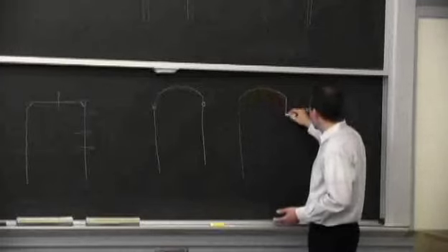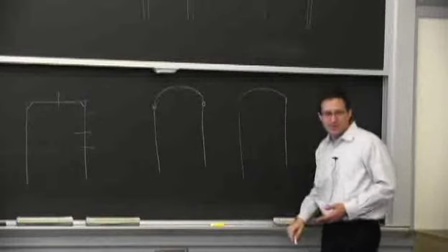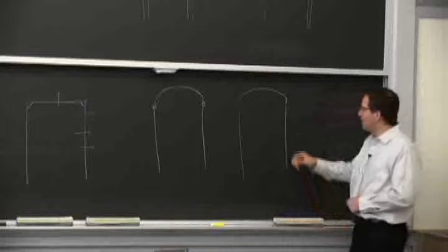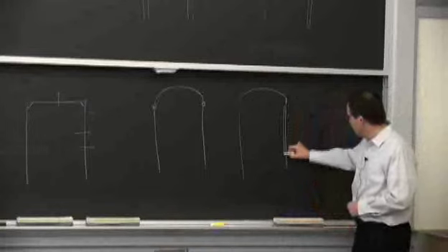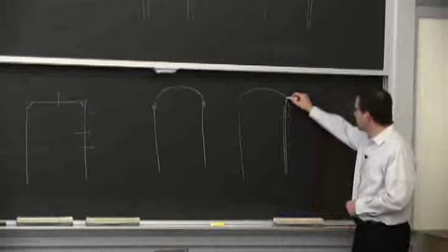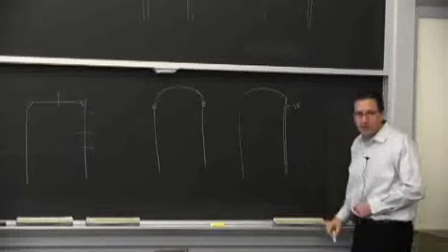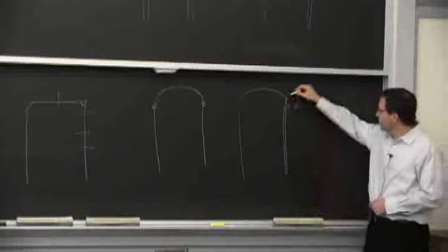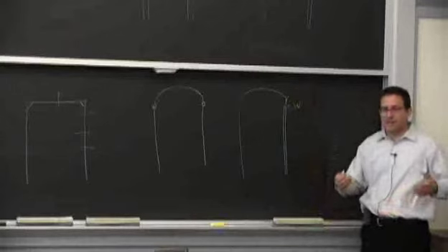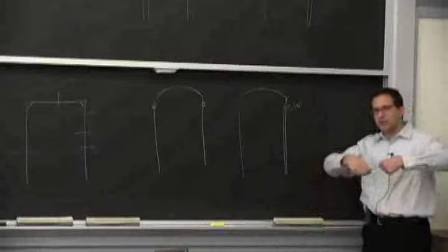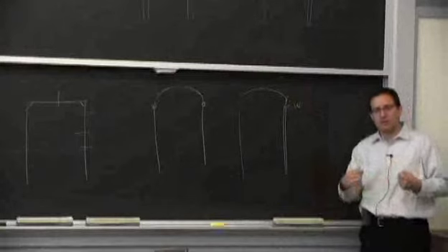You guys know that it's not that hard to make such a shape now with sheet metal. So if you do it, now you have a stress riser. So there'll be some opening of the metal, but you put your weld over here. So this corner is all that steel that you rolled and you formed into shape. It's super strong.